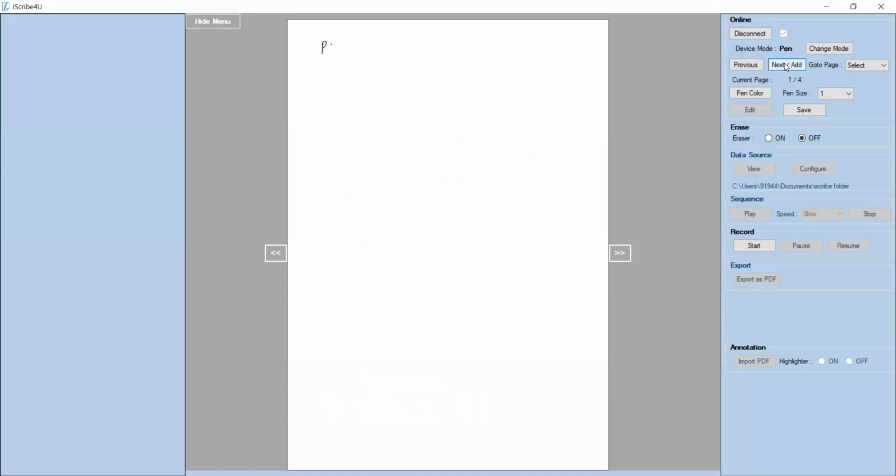So the peak overshoot derivation we are doing, we call it Mp. This is Mp derived. We have to derive an expression for this. So what is the formula here for the peak overshoot? The peak overshoot is defined as percent Mp, which is equal to C of Tp minus C of infinity divided by C of infinity into 100.